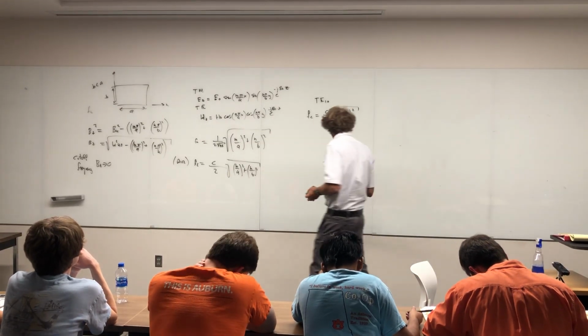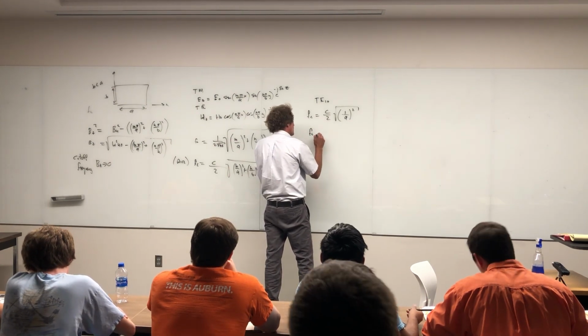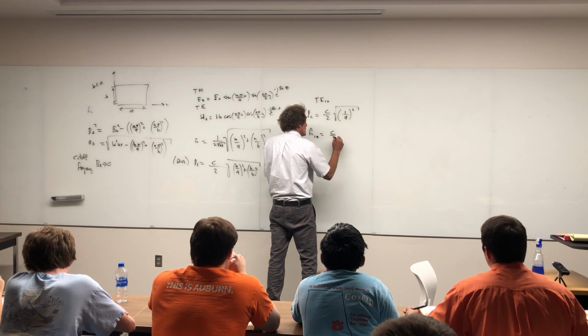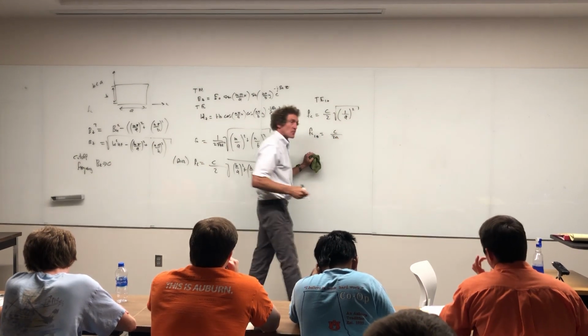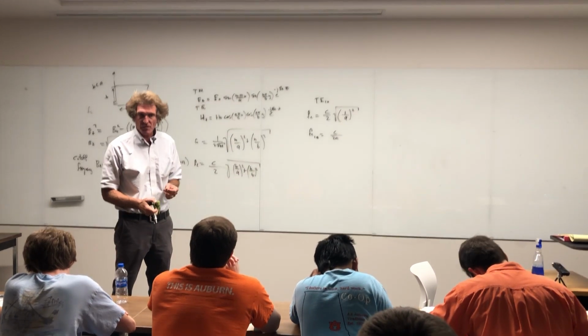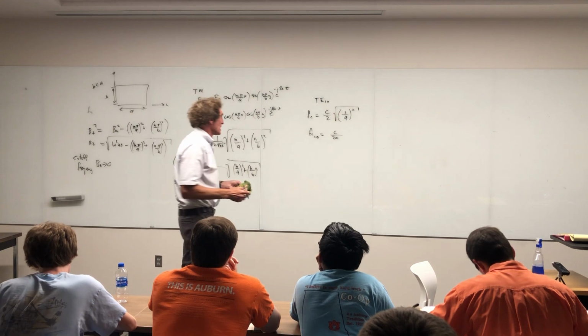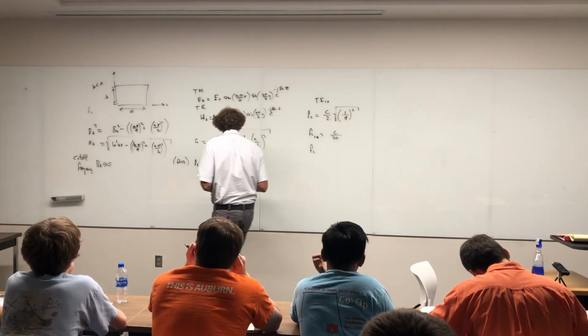So here, what do you notice that is? That's the lowest order. The cutoff frequency for the 10 mode is just c over 2a, c over 2a. That's the lowest order mode. c is in meters per second, a would be in meters. With me? After that, the next one would be what? Well, now listen to me.